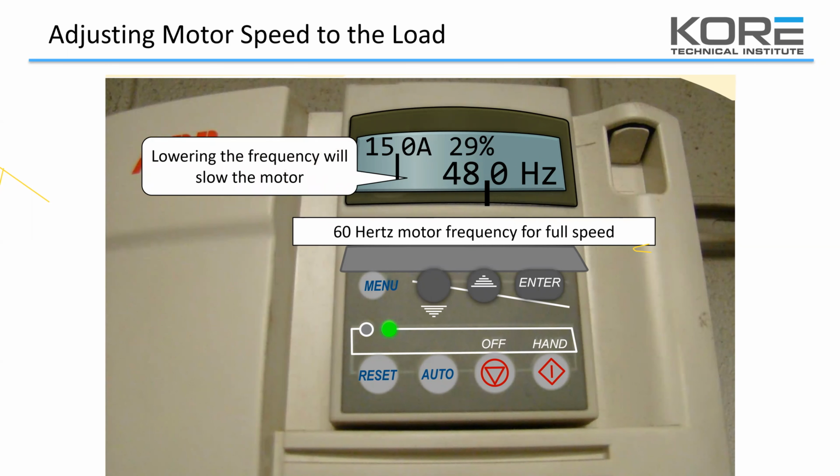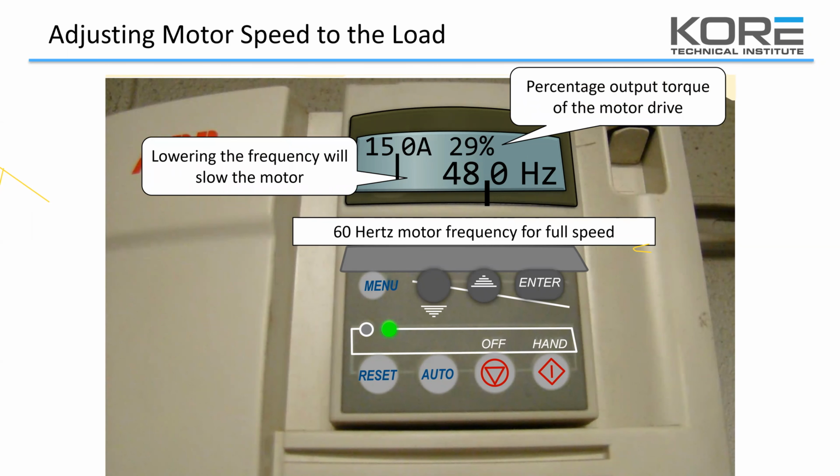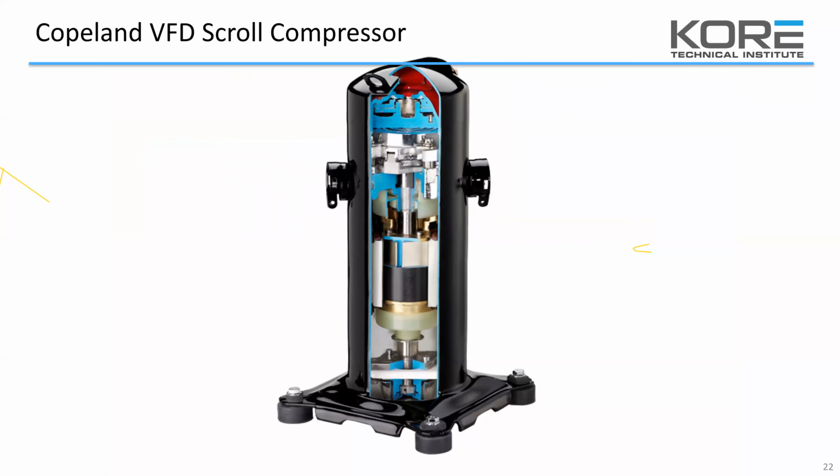So again, lowering the frequency will slow the motor. The percentage there is the percentage of the torque for the motor drive. Here's another capacity control method. It shows VFD on a scroll compressor in the slide, but you're not really going to see VFDs too much on scroll compressors.